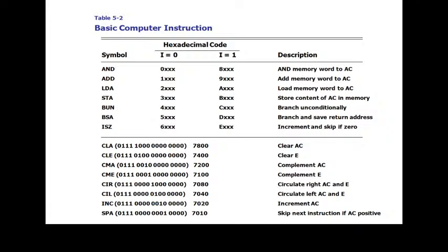But when we perform any addition or subtraction or multiplication, we can't have a guarantee that the contents of the accumulator will still be equal to or less than 16 digits. There may be a 17th digit, yes or no? So in order to accommodate that carry, we employed an extended accumulator.